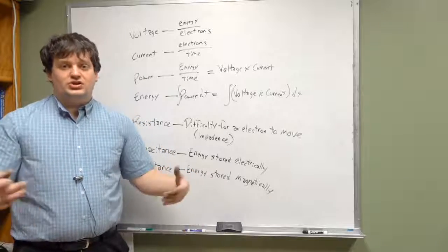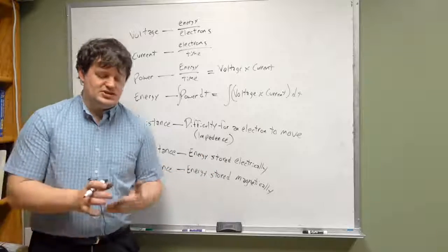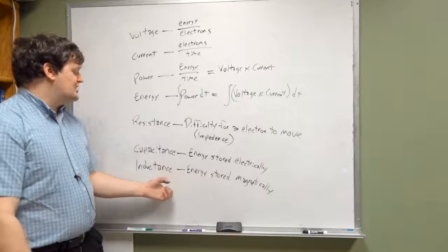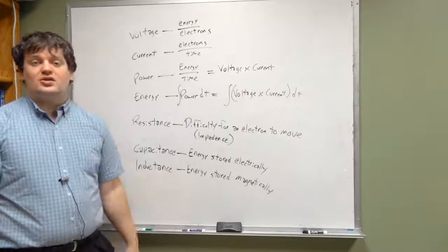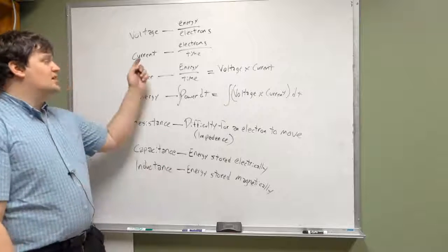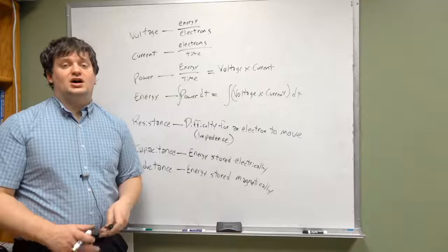Okay? We can ignore that inductance value. There are some variables that are associated with it by which inductance cancels out. Most of the time, I will point out to you whether or not an inductance is present. But in pretty much every circuit, if there is a current, there's going to be some small amount of inductance.